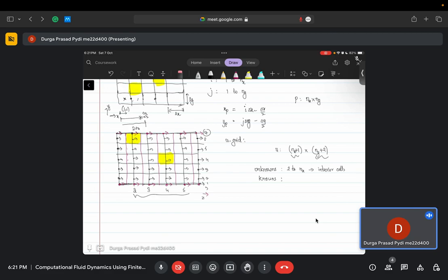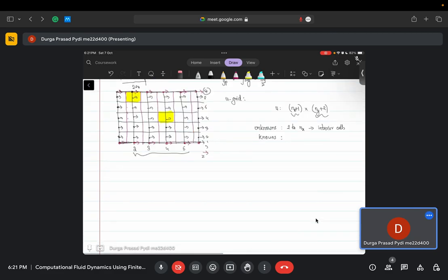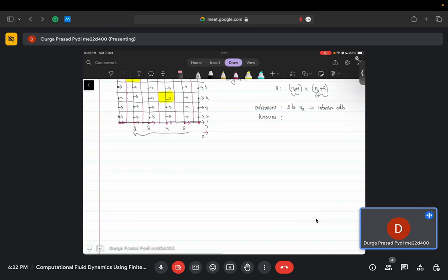So suppose you are solving a fluid problem, or at least we will consider the parallel plate flow, or maybe say boundary layer flow. So you know the boundary layer flow already. So you have a flat plate and then you have some uniform flow that is coming in. Now to solve this problem I will have to first define a mesh. So I will put a grid here, something like this. So what boundary condition will I keep on the outlet?